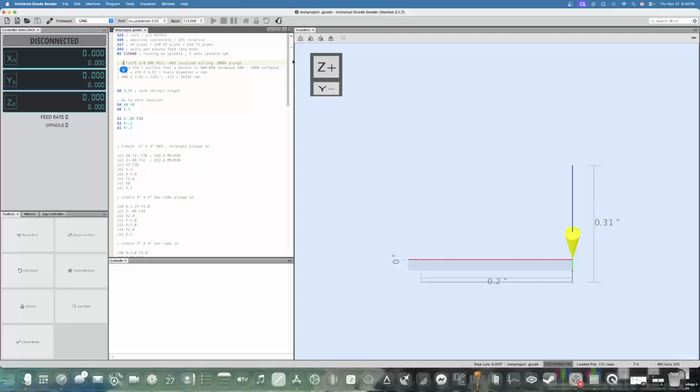The tool I'm using is a 2-flute, 1/8" end mill, flat tip. I'm using a 1,000th chip load for milling and an 8/10,000th chip load for plunge. And that's when people ask you what feed you're using, you should always list chip load. The reason for that is your inches per minute or millimeters a minute is a sum of 3 variables.